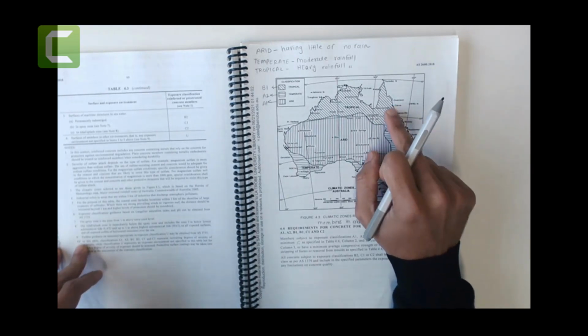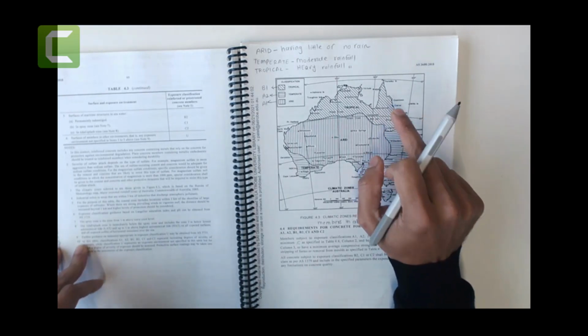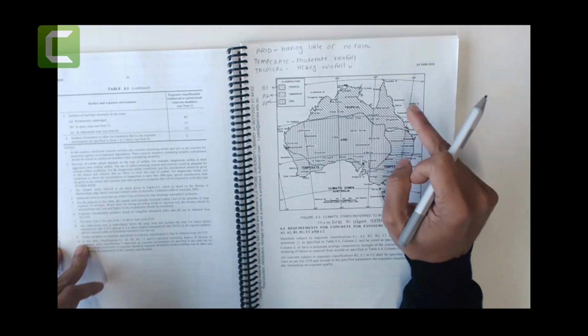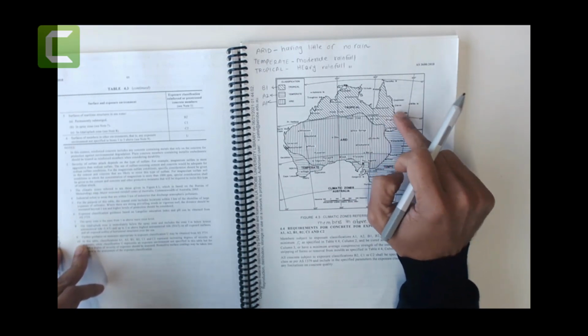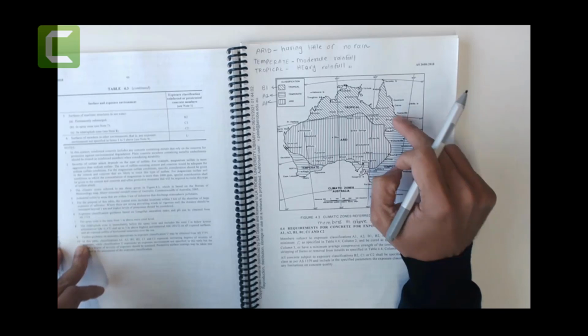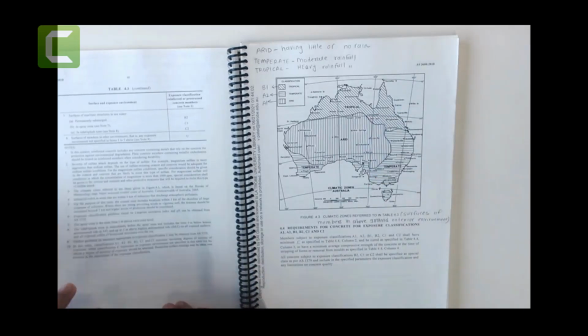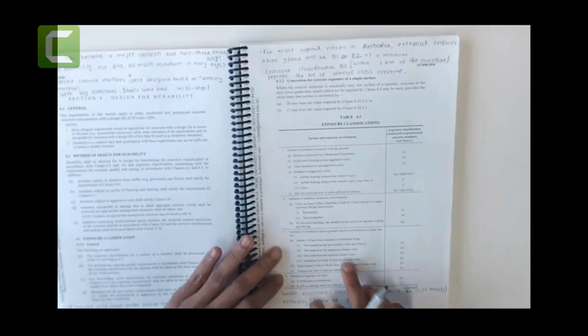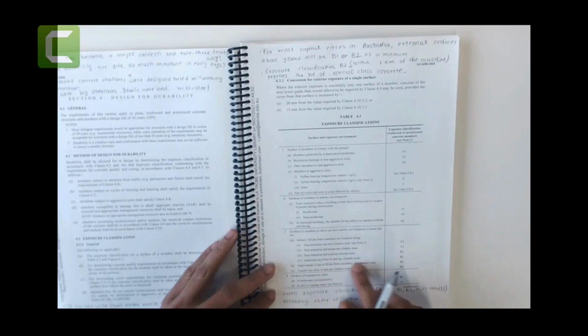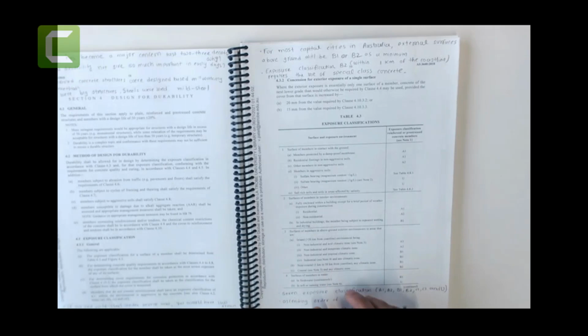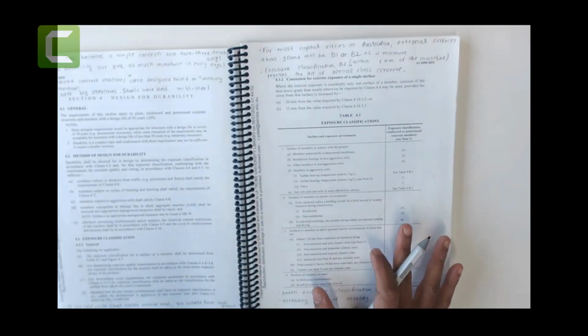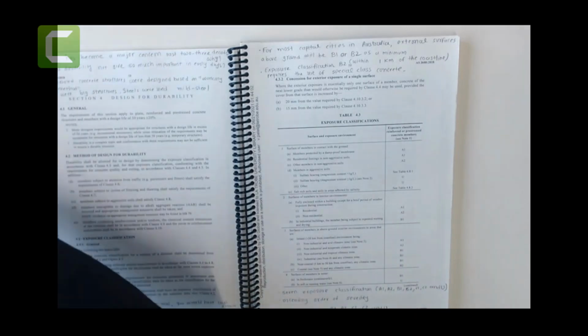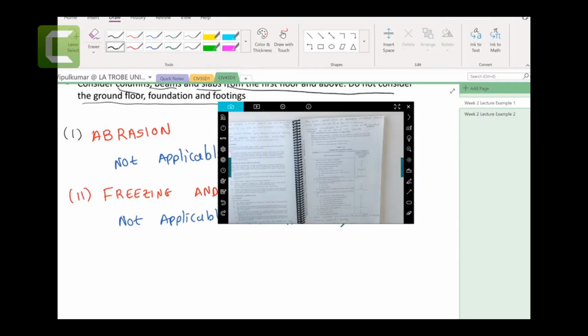So if you are designing the same building here, you need to provide more concrete compressive strength and cover if you have the same load. I hope it makes sense. So here you have classification for those near the coastline, 1 kilometer, B1, and so on. It's self-readable. I hope I gave you enough guideline to help you with exposure. So let's